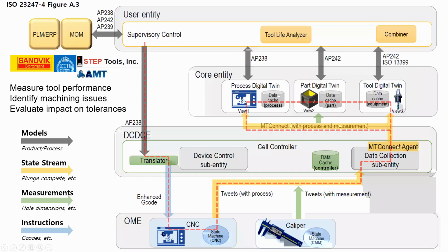I should use my laser pointer. The STEP-NC program has a translator that post-processes it into G code, but it also puts in STEP-NC related process steps and the actual part being machined and the actual tools being used. This way the machine will report this information in an MTConnect stream and make it available for, in this case, one digital twin application keeping 3 digital twins synchronized.